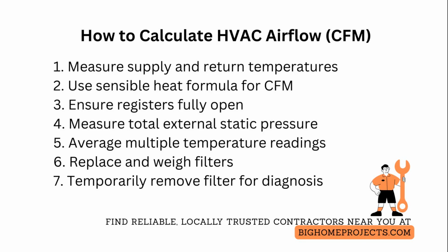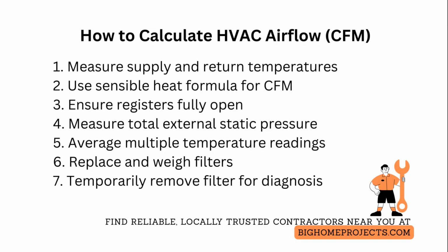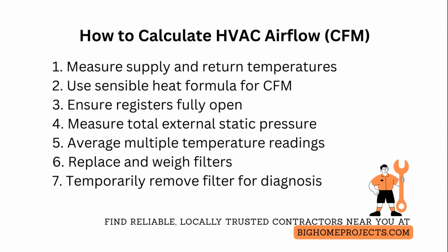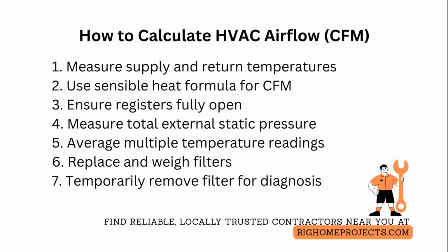Always account for fan calibration and static pressure, because inaccurate fan curves distort CFM estimates. When measuring, ensure registers are fully open, duct boots are not collapsed, and measure at multiple supply registers to find distribution imbalances. Balance readings by comparing measured register CFM to design CFM per room and adjust dampers incrementally, rechecking temperature rise after each change.